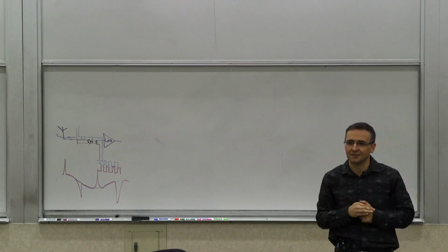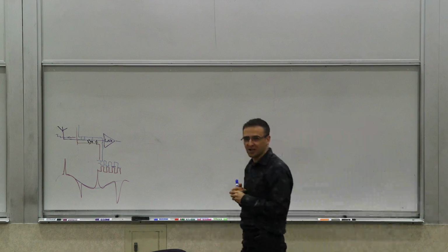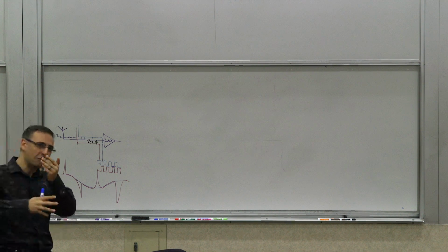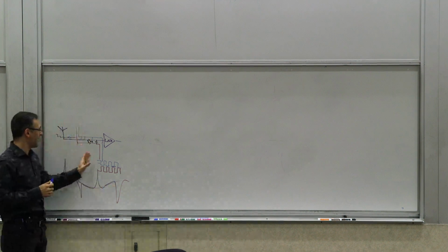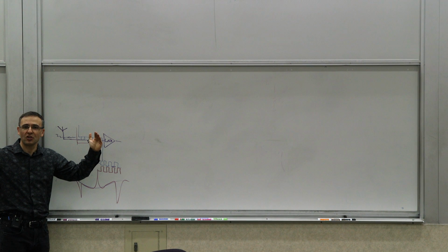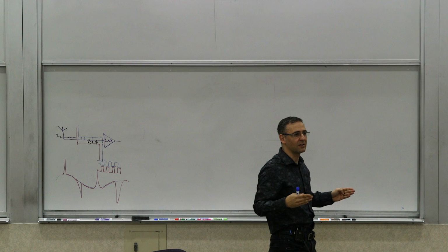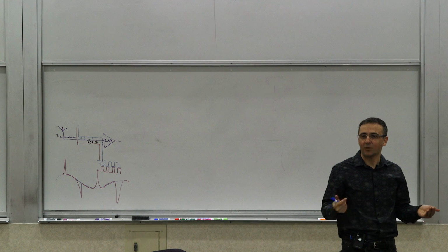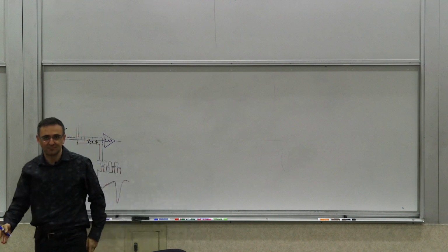Yes? If you have a capacitance coupling, you can use a conductor to help the coupling. So you can create two couplings that cancel each other, right? You're saying you're using a second coupling to cancel the first coupling. In principle, that's possible. In practice, it requires a lot of detailed work, because then you're not talking about one or two lines. You're talking about a big chip. There are lots of digital lines going everywhere. It's not just one line. There are lots of data lines going across that are not even periodic, so everything needs to be modified that way. So it's a major overhead, and also a difficult analytical thing to do on a large number of things. Maybe if it's one line, yes. So what else can we do?